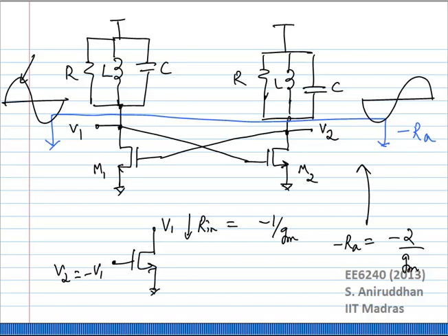However, what we know is they are both completely identical, but there is an initial charge across one of the capacitors. Okay? Then that initial charge will actually create a mismatch in voltage between these two nodes, and therefore it basically turns on one guy and turns off the other, or vice versa. As long as you create a slight mismatch, it will move away from that metastable point and try to go to the other side.